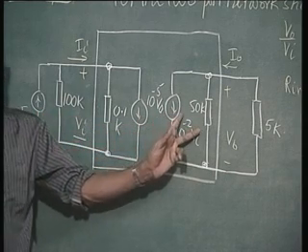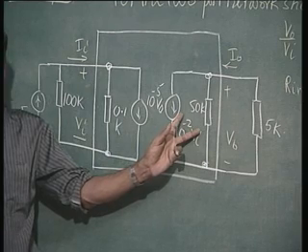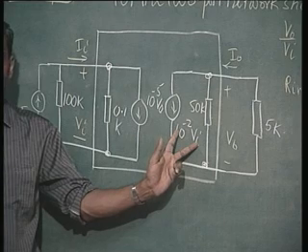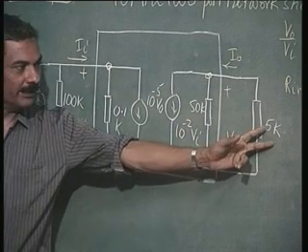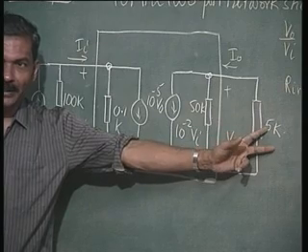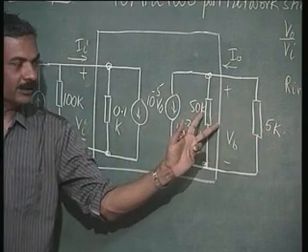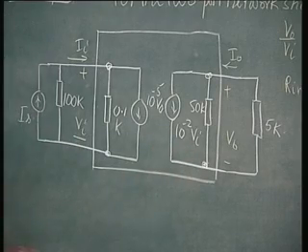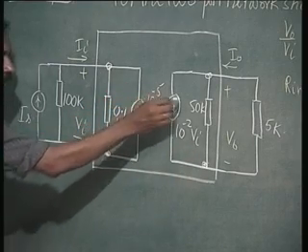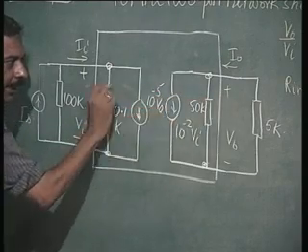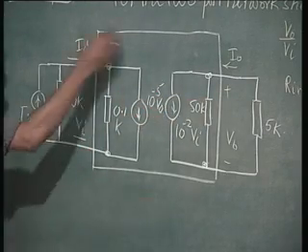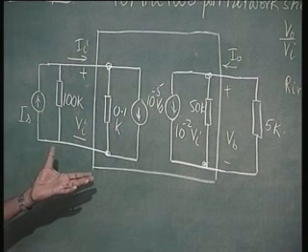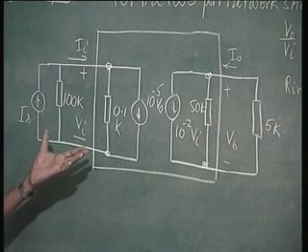At this point, the control source, whether it is correctly represented as a current source or not, can be again justified by comparing it with the load 5K. So 5K is very small compared to its source impedance of 50K. So it is correctly represented as a current source. Now if these are the currents due to output and input respectively, then this whole representation can be identified by comparison with what you have learned with Y parameter.